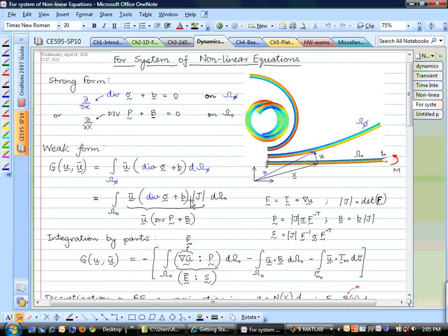Now what are all these quantities? So for large deformation problems, you should remember that we had defined this quantity F, that is deformation gradient, which is identity plus gradient of displacement, and this Jacobian, or the determinant of the Jacobian, this F is nothing but the Jacobian from the undeformed configuration to the deformed configuration. That's all that this F does. And this first Piola-Kirchhoff stress tensor, you don't actually have to find out how, or this thing did not drop out of the sky or something.